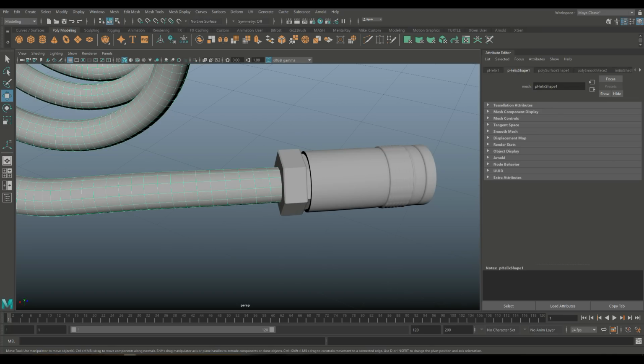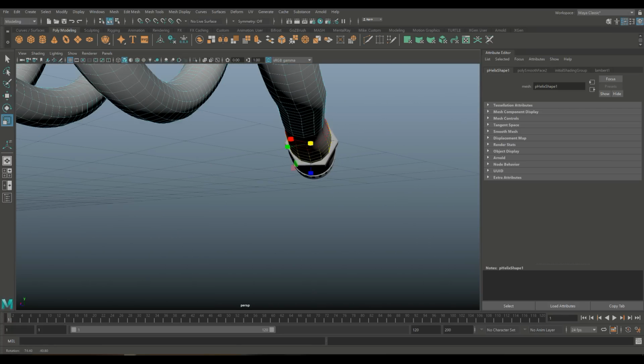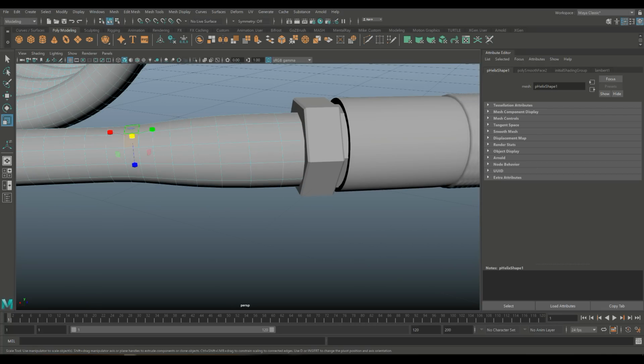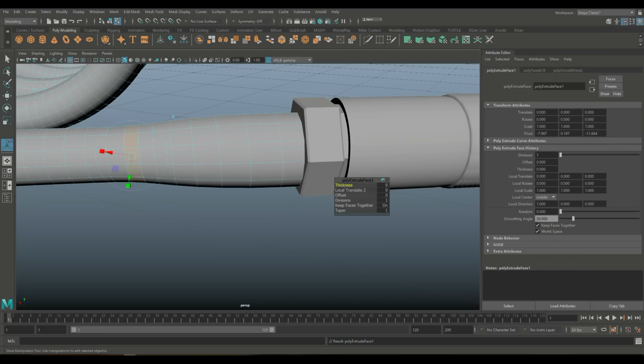What we'll do here is right click, go in here, and take these faces, right? And I'm going to hit B for soft select, hold on B, kind of drag it back in. And I'm going to hit R to raise that out like this. That looks kind of neat, all right? And then we'll hit B to turn that off, and go into this section right here. And we'll hit Control E to extrude. We'll hit R to scale that out a little bit.